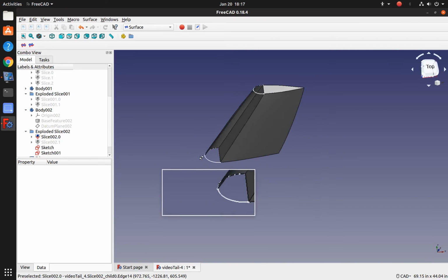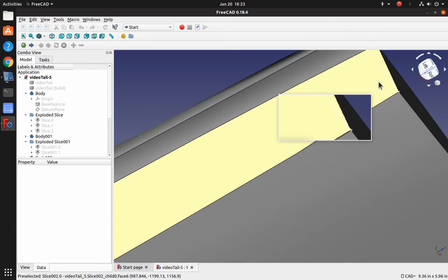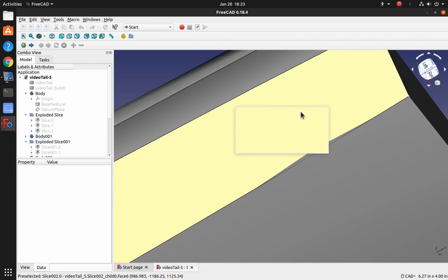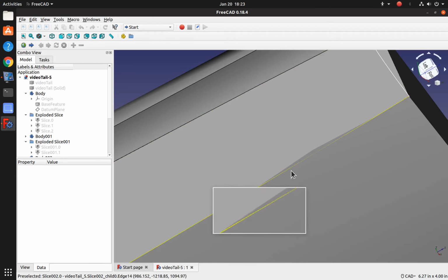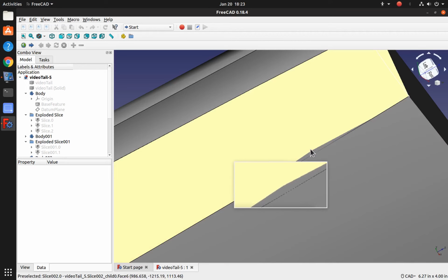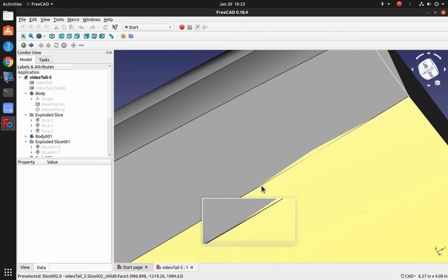That looks pretty good. I do have a little bit of a problem. There's an error that FreeCAD made when it did a slice for this hinge face, and you can see it kind of sticking up here. So this face is actually sticking past the hinge a little bit, and then I think it folds right back to this edge. At least that's what it looks like.